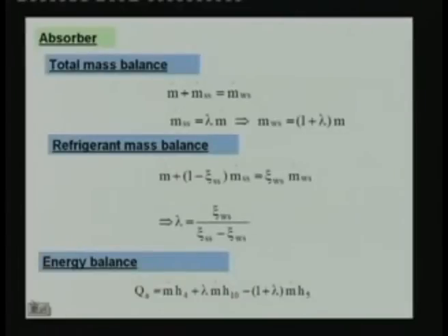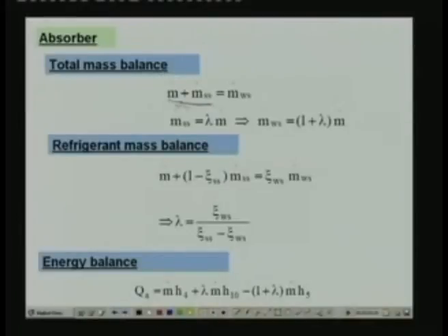Now let us come to the absorber. In the absorber we have both refrigerant as well as solution. Okay, so first let us apply the total mass balance. This is the total mass entering into the absorber, this is the total mass leaving the absorber.